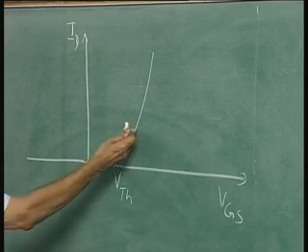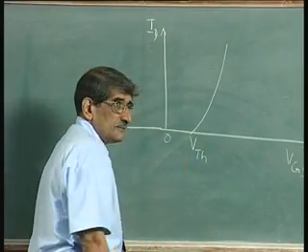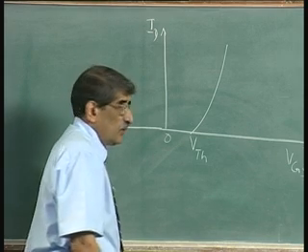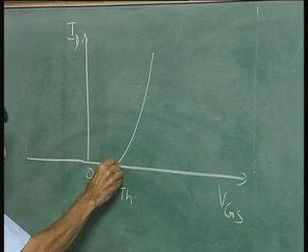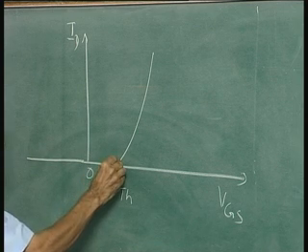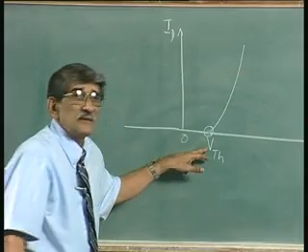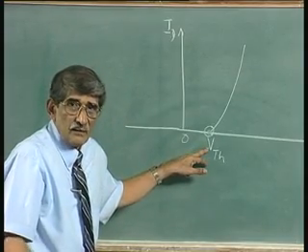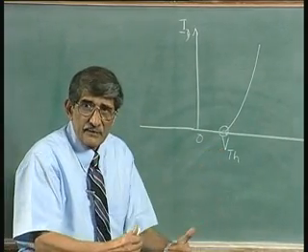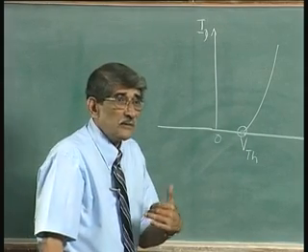Now, we call this the square law right from the threshold voltage, just when the channel is pinched off. What actually happens in reality is, when you go right up to threshold voltage, it is still not completely off. So, what we are looking at is this region around threshold voltage, particularly what happens when you go below that, how it is turning off.